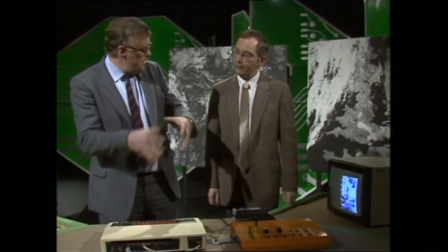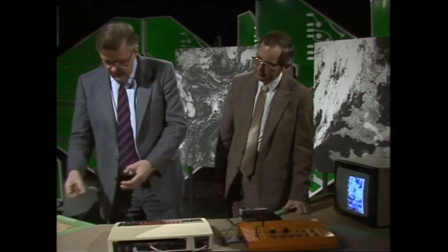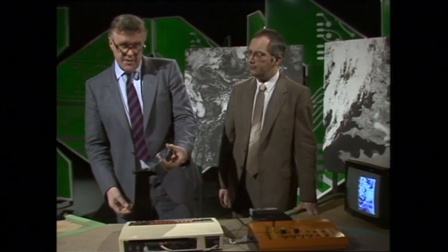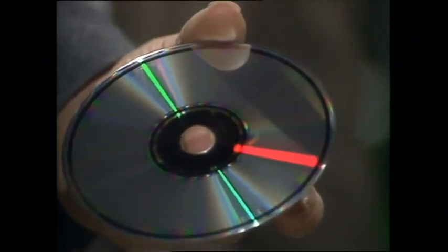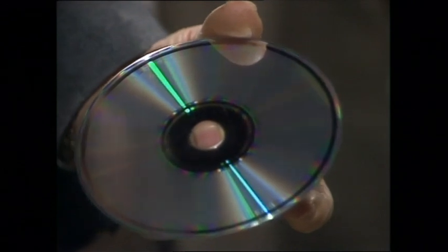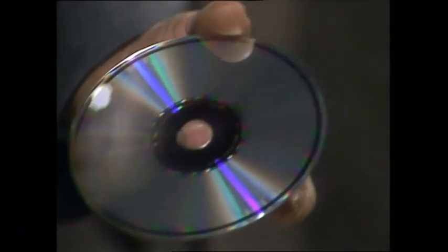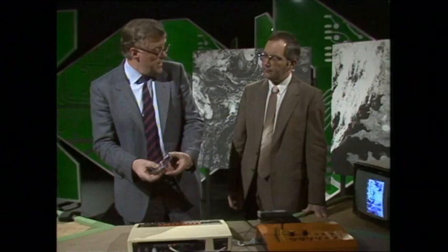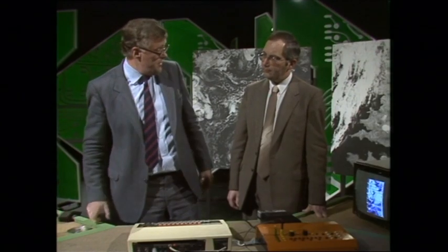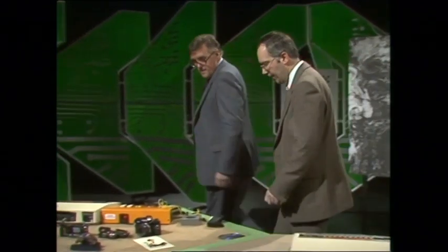Well, that was intermediate frequency sampling at about 1,000, but many people are familiar with this. It's a digital disc, and the highest frequency you're going to meet, or you can hear, is about 20,000 cycles per second. And on John's rough rule of thumb, on a digital disc, they're taking about twice that, which is 40,000 samples every second to get the high quality out of a digital disc. Over here, we've got some demonstrations of very high-speed sampling.